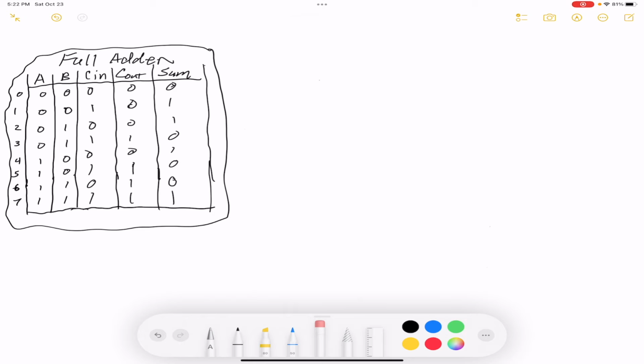So now we're going to draw the Karnaugh maps for the adder circuit. A Karnaugh map, or K-map, is a tool that hardware designers use to map what's all in this area here to the left, the truth table, into a form where we can derive the equations for our circuit. So you need a Karnaugh map for each of your outputs. We'll begin with carry out.